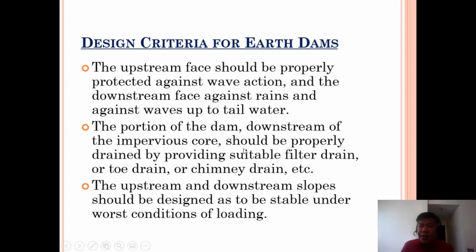The portion of the dam downstream of the impervious core should be properly drained by providing the one mentioned earlier in the previous slide, the filter drains. Or sometimes it's called toe drain, the chimney drain, etc. But those are all drains.